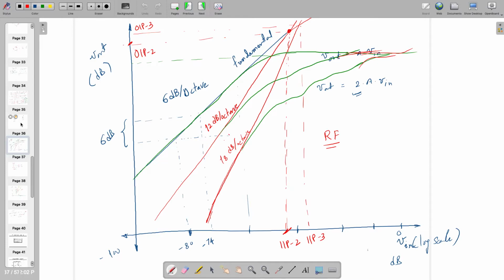30 dB per octave. You should not miss the unit, which is dB per octave, right? So any doubt in this one? Look at these plots. These are actually working when the input is in log scale. On both sides, I should write dBV because it's not a ratio, it's just output and input.